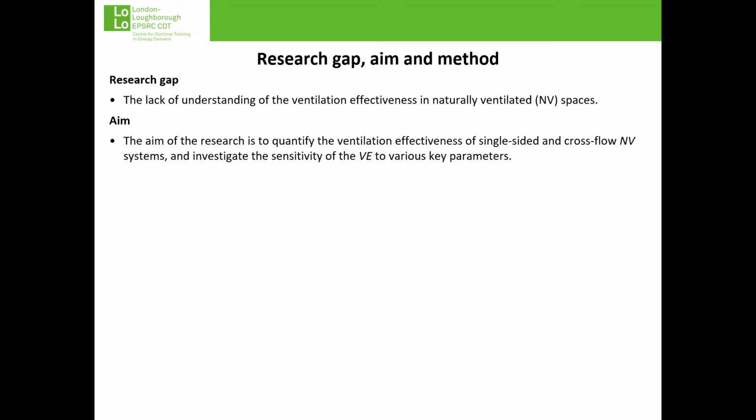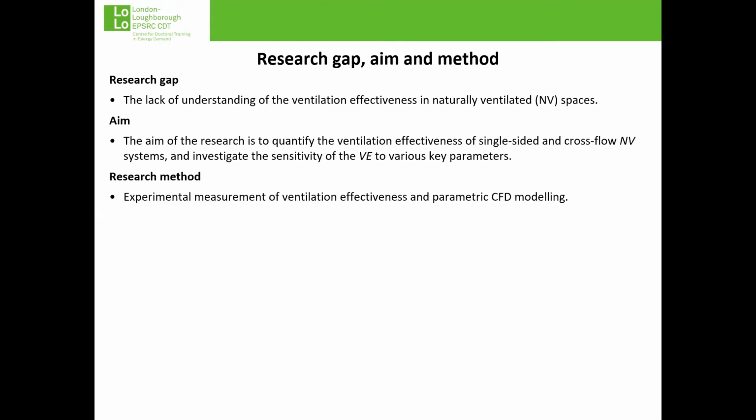Additionally, it is also aimed to determine the influential parameters and the significance of the influence of those parameters on local ventilation effectiveness. In this study, experimental and numerical methods were used in conjunction to achieve the objectives of the research. I was privileged to conduct the data collection in the IEQ lab of the University of Sydney. The experiments aimed to quantify the ventilation effectiveness of the NV systems employed in the lab and to provide the data for the validation of the CFD models, which were later used in the parametric CFD analysis.